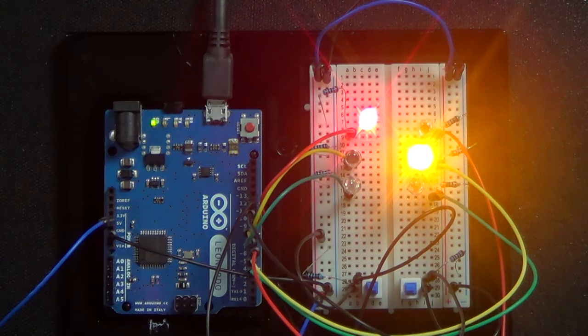And there are 2 things I wanted to show you. First of all, how you can do sensor inputs, which basically I'm looking at these as being sensors. I mean, a car is there. It could simply be a contact closure. And to control the output lights, you could take any output, do an SCR and a couple other layers of stuff, to relays or whatever, to control lights. You could truly control a traffic light with the Arduino, which is that little bit of code that I just did, if it was a basic traffic light. And you can see how you can add things in there.